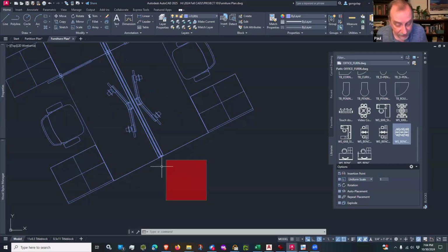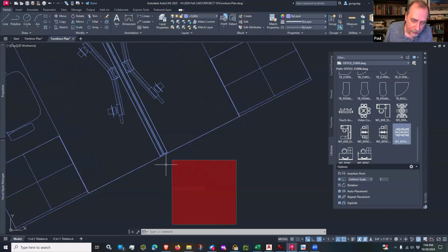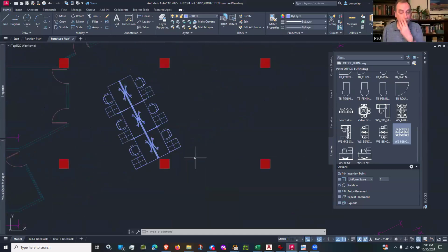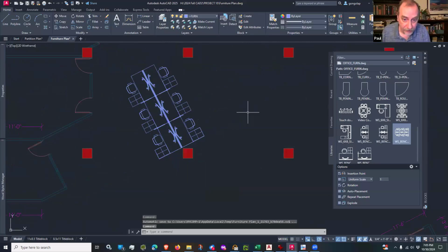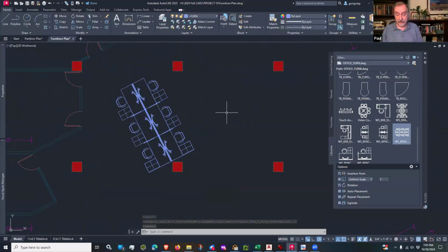And that flexible cable is called a whip, WHIP. The power runs through it, and also phone and data lines come down through it as well. And so it comes down through the column and then whips into the spine of our workstation. So in general, when you are locating workstations in your career, try to find places where the workstation can be powered easily. But sometimes you can't.